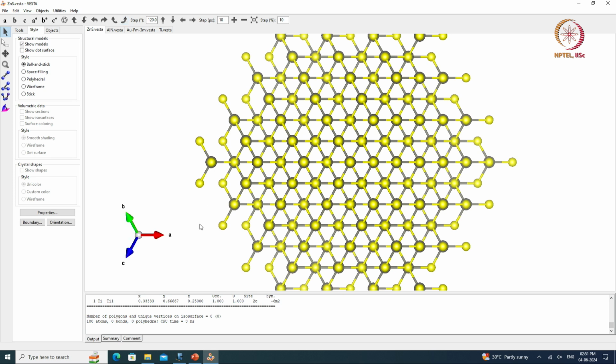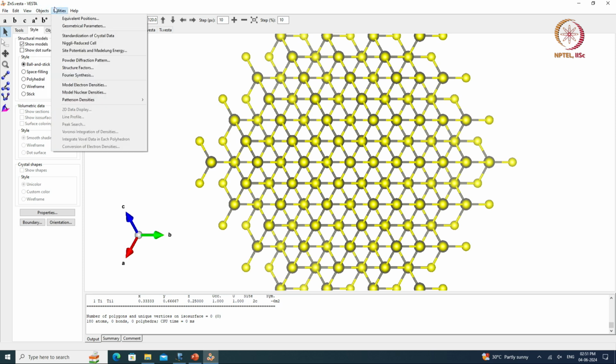You can pay attention to the axes. I rotate it again, the axes have changed, but it does not seem like anything in the crystal has changed. So there is a 3-fold axis of symmetry, and in fact that passes through your origin. About the 1 1 1 axis there is a 3-fold axis of symmetry, but since it is cubic, about the 1 1 1 bar also. I can show you that very quickly.